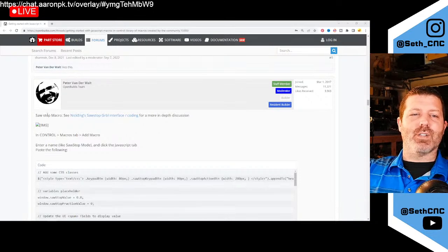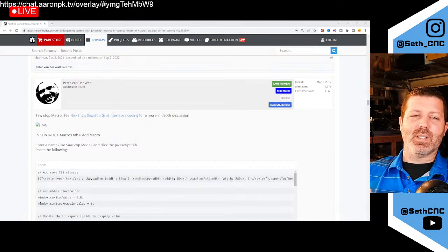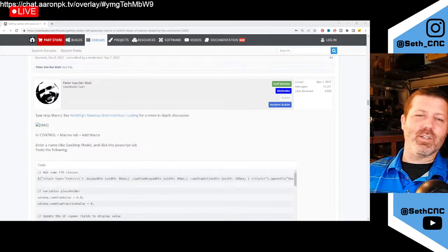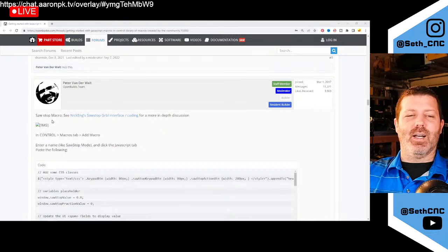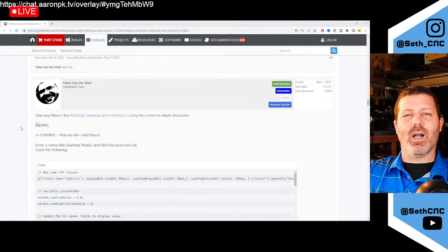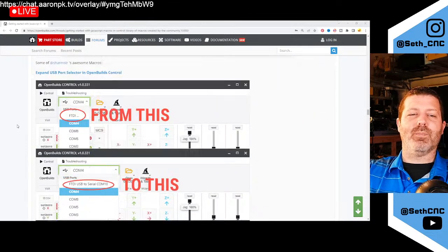There's a macro here called the saw stop macro, and the way it works is kind of like how the SawStop works. If you hit material that is conductive, it basically stops, but it has to be grounded as well. So it may or may not work with human flesh. It all depends on how well you're grounded. Whereas on the SawStop, it's using the table itself as the ground, but not all CNCs have a metal bed. So this saw stop macro only works in certain instances. But it's a neat little feature, right? Where you can say your CNC operates like a SawStop.